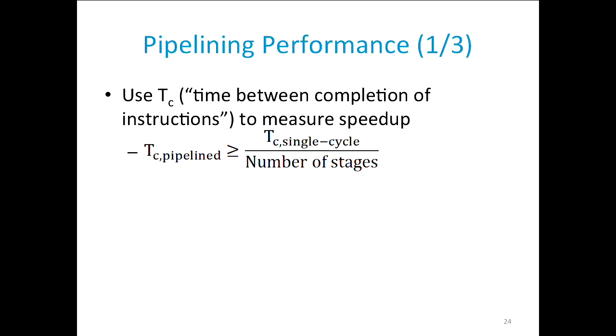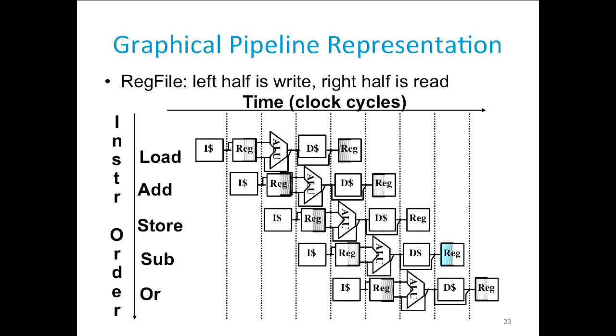So going back to, what's the benefit of doing this? Well, the question: if you were trying to write and read the same register, as in you load it into register S1 and then try to add with that register, if you haven't rewritten it yet... Right. So the question was, what happens if I'm writing register 3 here and I'm reading register 3 here? Or even in the next add, if you're writing to register 3 in the load and then trying to add using that value. Good catch. We'll get into that in a few slides.